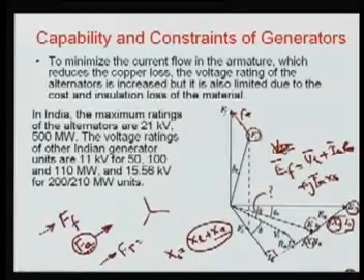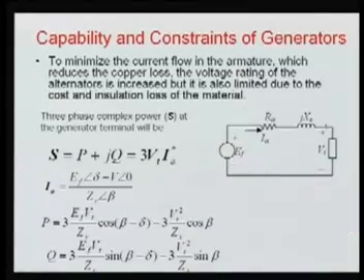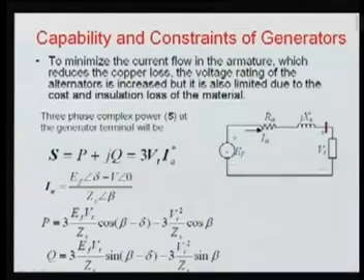Now this terminal voltage is the voltage of your alternator. So the reactances and EF we have written, this is your equivalent diagram of an alternator. Now this whole rotating mass can be represented by this equivalent electrical circuit, where E is the field EMF, which again depends upon the field excitation level. Then this current IA is your armature current, and it is flowing through the winding resistance and this XS, which has two components. One is the leakage, the actual inductance of the coil, and the other is the armature reaction component, so it is called synchronous reactance.